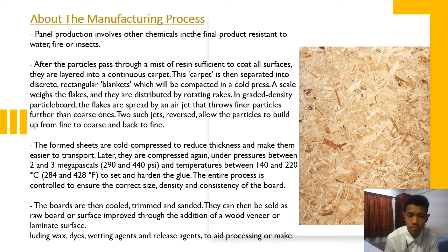Later they are compressed again under pressure between 2 and 3 megapascal, 290 and 435 psi, and temperature between 140 and 220 Celsius, to set and harden the glue.